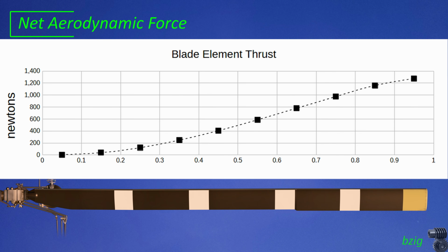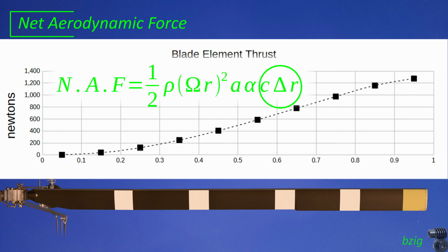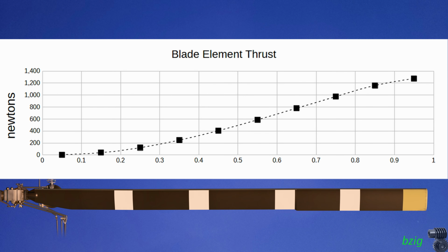And note, I'm not integrating the area under the curve. This is because I already included the blade section length in the equation. The total force is the sum of these numbers rather than the integral.